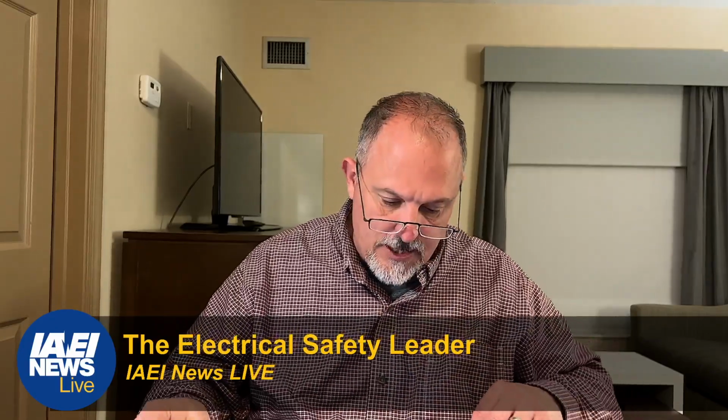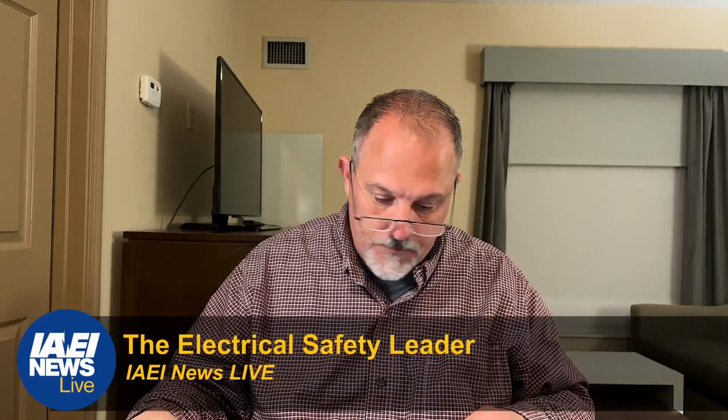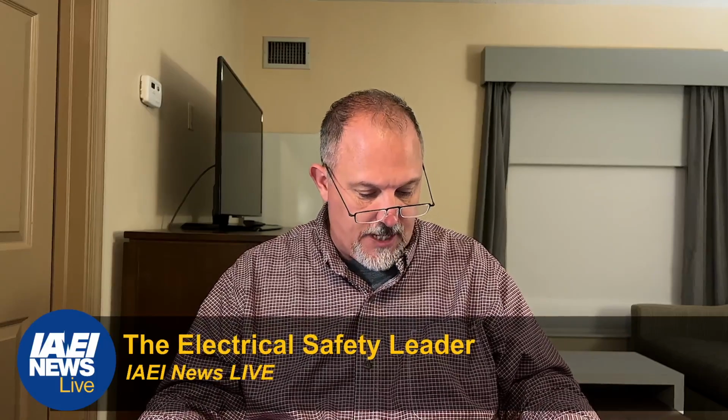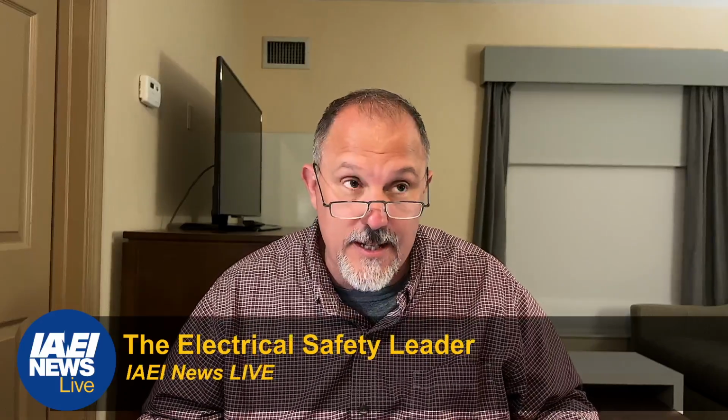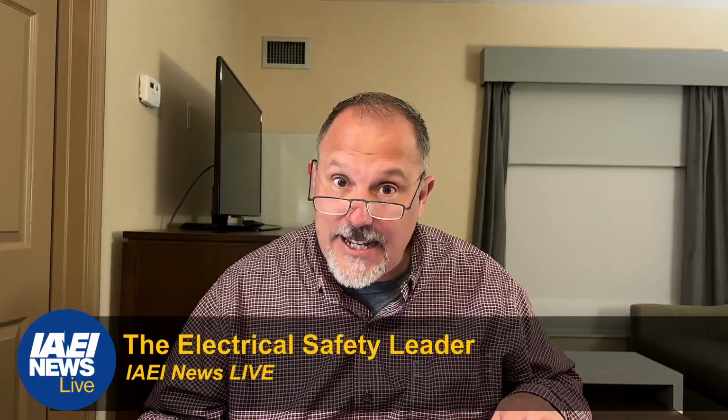So 680.5, let's go back to 680.5. It is still ground fault circuit interrupters and special purpose GFCIs. General: the GFCI and special purpose GFCI requirements in this article, unless otherwise noted, are in addition to the requirements in 210.8. In addition to, not supplementing or modifying, but in addition to. 150 volts or less to ground: where required in this article, ground fault protection of receptacles and outlets in branch circuits, 150 volts or less to ground, 60 amps or less, single or three phase, shall be provided with a Class A GFCI. That's your 4 to 6 milliamps.